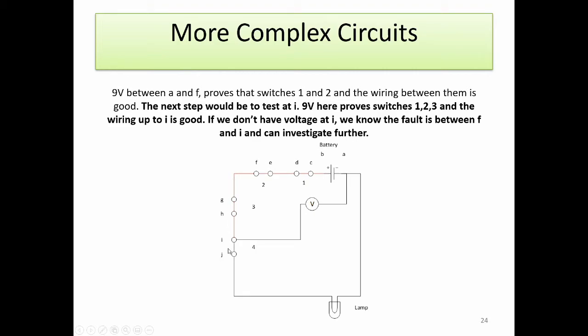The next step, we could test at I. If we don't have voltage at I, then we know the fault is between F and I, and we can investigate further.